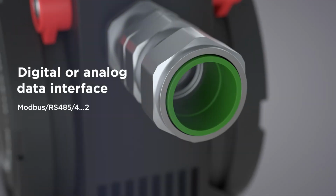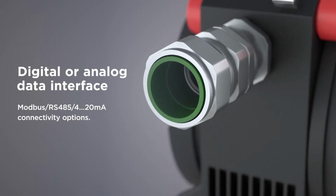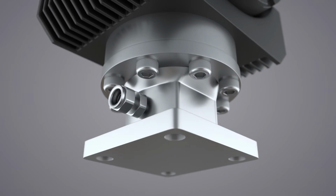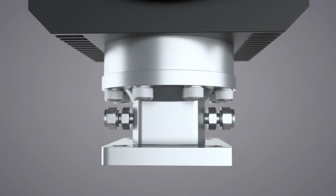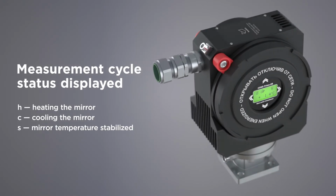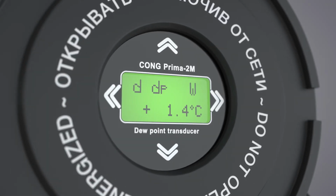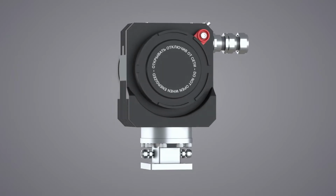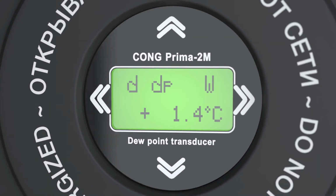The Kong Prima 2M is easily integrated into any telecommunication system via digital output using a Modbus protocol or via 4-20 mA analog communication. The Kong Prima 2M dew-point analyzer is compact, lightweight, and has 3 measurement modes: water dew point mode, hydrocarbon condensation temperature mode, and alternating mode for measuring both the water dew point and the hydrocarbon condensation temperature alternately. The operating menu can be accessed and controlled by means of 4 magnetically activated buttons using a magnetic key.